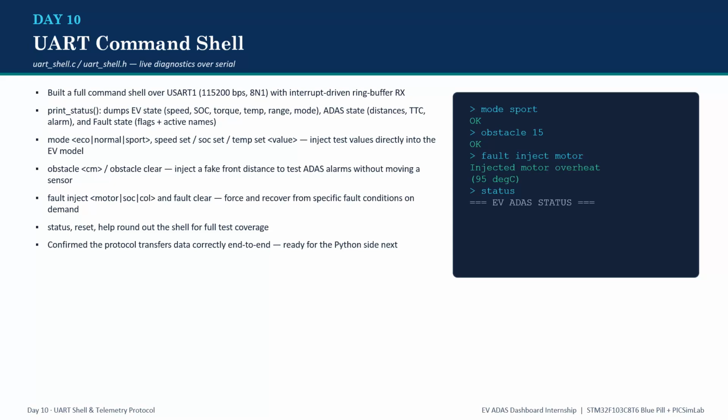I can set the drive mode directly with mode eco, mode normal, or mode sport. I can inject test values with speed set, SOC set, and temp set to test the EV model deterministically without moving the potentiometers. I can inject a fake obstacle distance with obstacle followed by a number to test the ADAS alarms on demand, or clear it with obstacle clear.